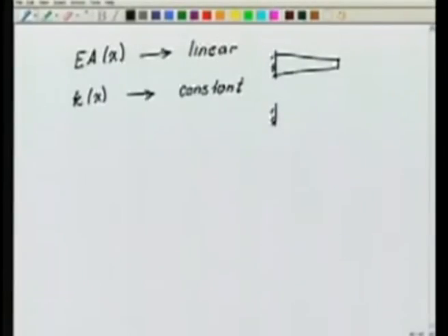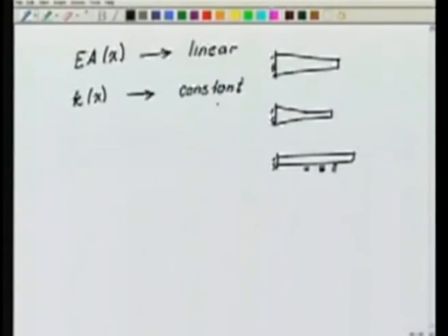That is, I could have this kind of a tapered bar, or I could have elastic support in only a particular region of my member. So, as long as it is satisfied piecewise, we are happy. So, Kx has to be piecewise constant. We are going to fix it, which is what our code is capable of handling, the finite element program that we are going to develop.